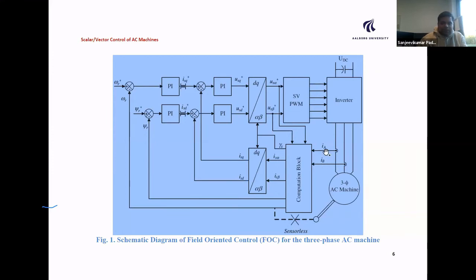So we try to get the two parameters of the current from the phases which are given to the three-phase induction machine. And here we can calculate two parameters. One is the flux linkage in your rotor, by equations. Of course, we can also calculate the rotor speed. All this can be done if you know the exact dynamics of your electrical induction machine.